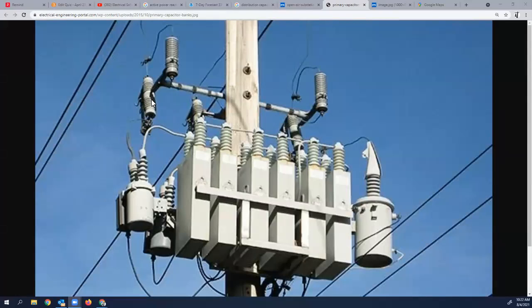If I had a guy in a bucket truck that de-energized the bank, opened these switches, took these high side risers off and installed his rubber goods, I'd be okay with a person climbing up here and doing work. Can he do it by himself just climbing? I seriously doubt it. No, it's too bulky. This framing style is not ours, that's obvious, and it's not really good. It doesn't seem to be much distance.